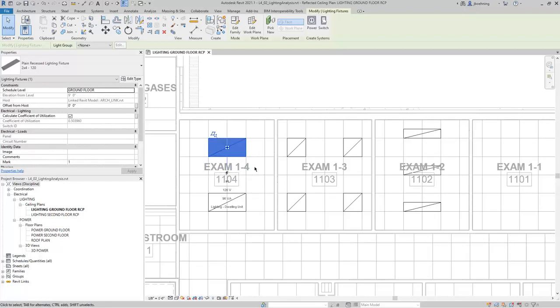You may also have light fixtures that are unhosted and maybe they're placed slightly above the space. And so all those things can go into account and cause your average estimated illumination to be incorrect. And so you want to make sure that they're placed correctly and that they are in the space. Another thing is we want to make sure that the light source is enabled.